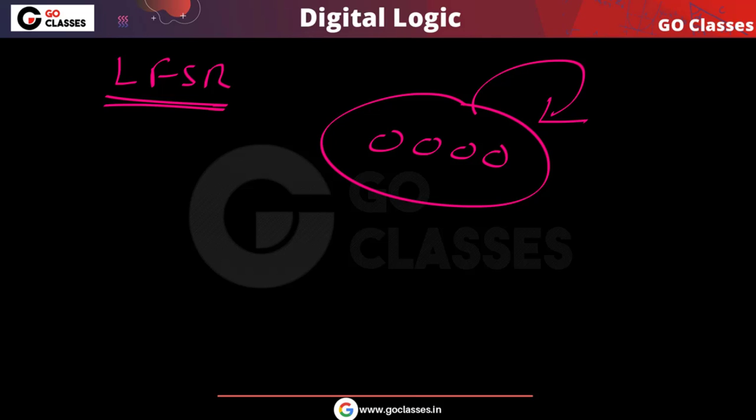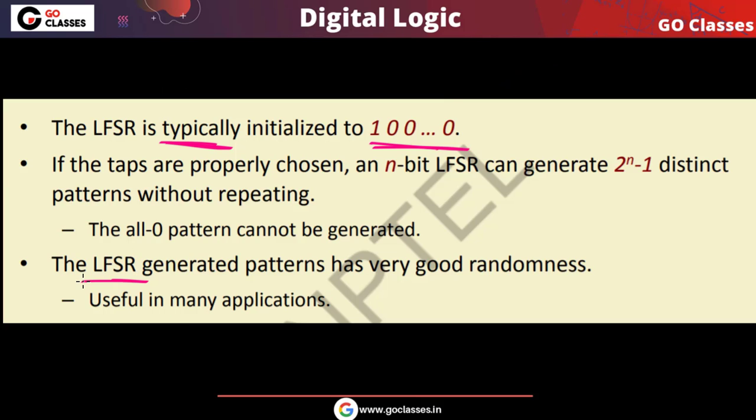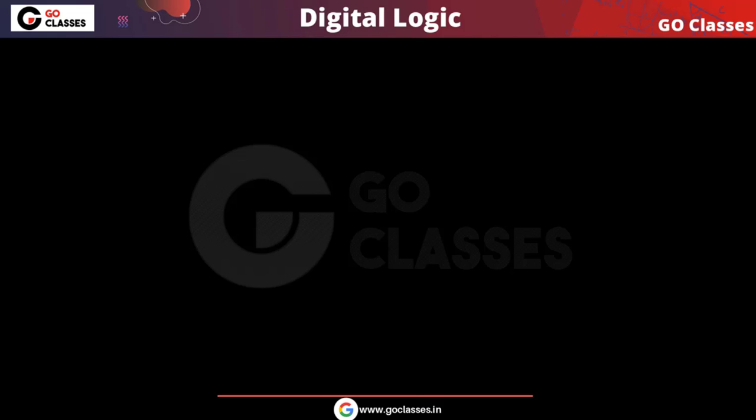Because these are the applications. The linear feedback shift register is, first of all, generating 2 power n minus 1 distinct patterns. Also, you can use this linear feedback shift register for randomness. If you want to create random numbers or a random sequence, then you can use this linear feedback shift register.